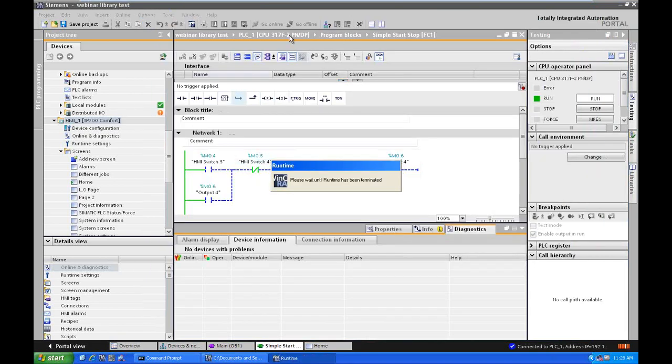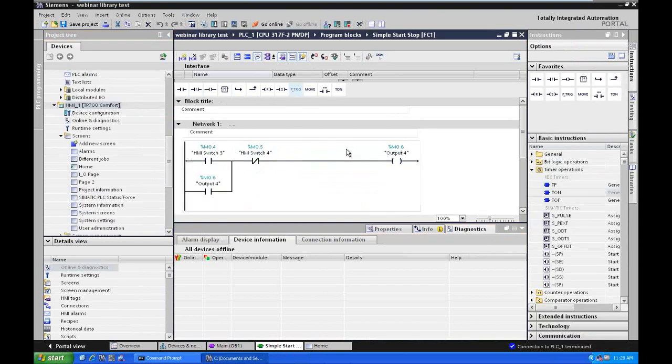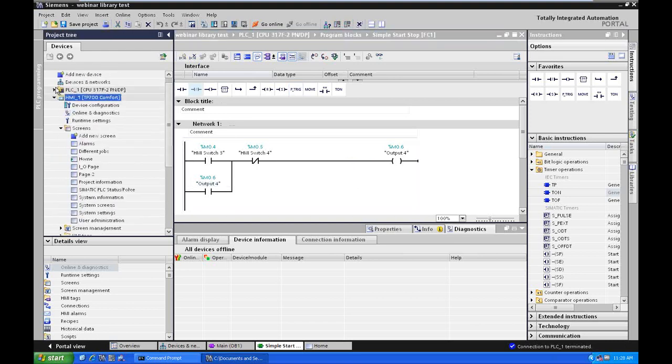Integrating was very simple. Didn't have to create any particular tags in the HMI, only create them in the PLC, and then use what I need in the HMI. So this way the HMI is not loaded up with every tag from the PLC. It's only using the tags that you need. So you develop the screen object, then you add that object, the tag parameters to that object from the PLC. Because this is all one software package, it's a simple thing to do.